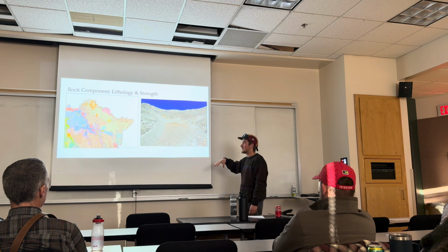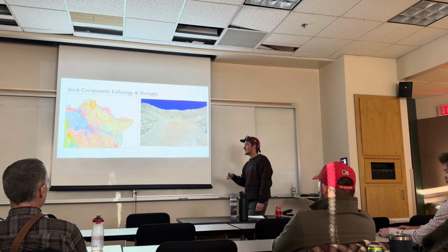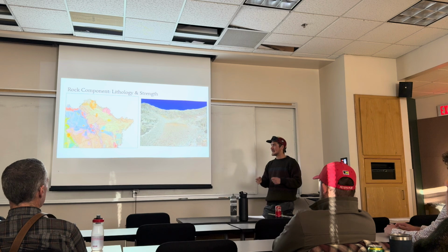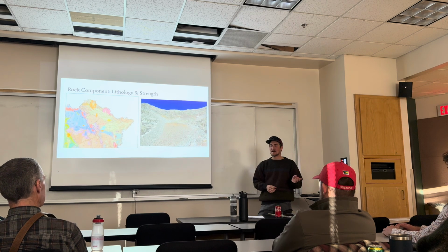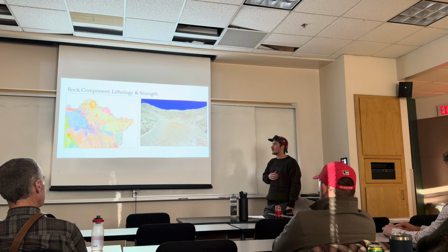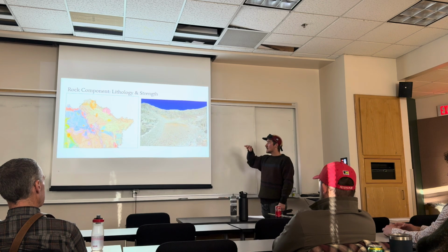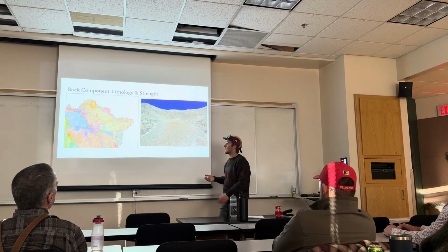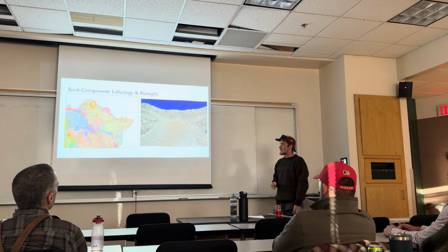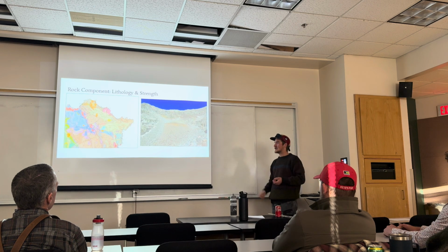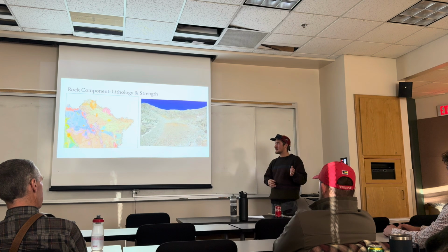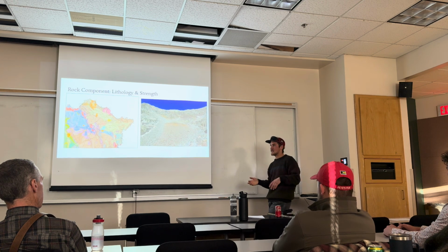So this is what I was talking about, the issue in my survey. I have lithology on 142 of these, but I focused my lithology surveys on ability to beryllium-10 date, which would be super useful. We just never got to that, but someone else can do cosmogenic data on these, and what that could tell you is at what time these rocks were exposed. So what time they were released from the head wall and have been exposed to the sun. I can tell you which ones we can beryllium-10 date, but that means I would just call things a granite or a gneiss. I wouldn't differentiate a gneiss that's an amphibolite or a schist with lots of mica and biotite. As we know, those two things are going to have very different failure mechanisms.